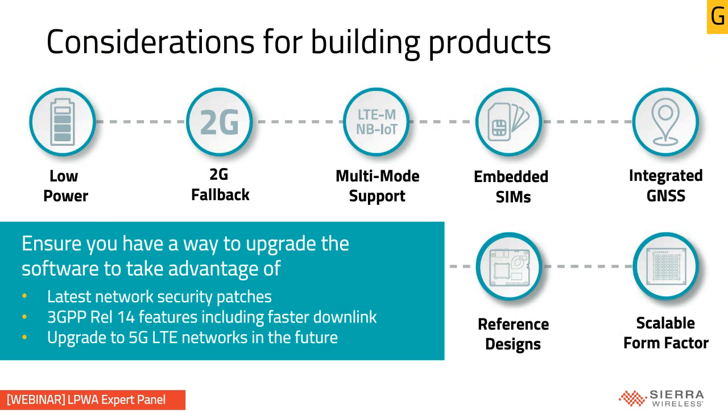But you need to consider beyond the 4 Cs. Application developers need to look to see what kind of coverage, for example, they have. Maybe they don't have LPWA coverage in certain areas, so they should consider 2G fallback, or maybe they need to consider whether LTE-M and NB-IoT are supported everywhere, so they might need multi-mode support.